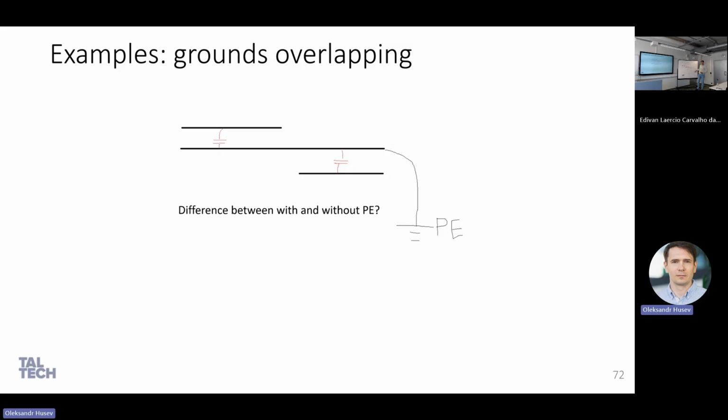But if you ground it, you made it neutral, which means the charge distribution will not work in this way anymore. In this case you will have a parasitic capacitor between this and this, which is much smaller because you don't have any overlap. That's why there's such a small effect, but in one case it may cause this value. We saw oscillation related to this big capacitor between windings, and it had a crucial impact. As soon as we grounded, it disappeared.